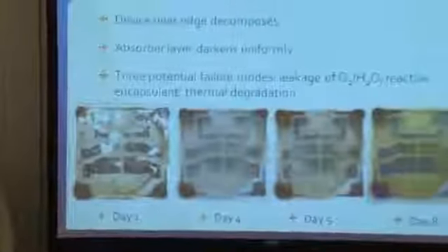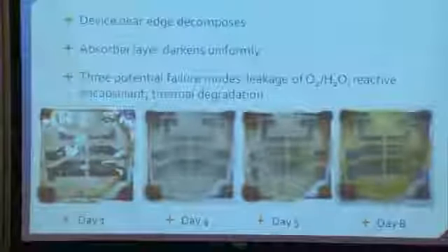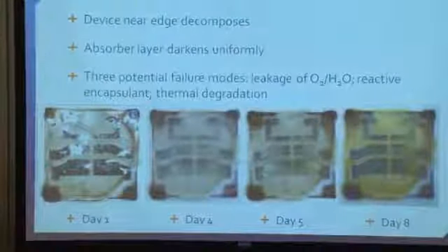For the quantum dots, it's a little bit less clear if there's a reaction with the EVA or not, because there are both degradation or color changes from the outside that particularly affect the outside, and there are also color changes that affect the whole device. So then it's either the quantum dots are somehow changing, or there may be some kind of reaction with the encapsulant. But when we took the SEM images, the EDX aspect of it was not working, so it was difficult to do any kind of elemental analysis there.